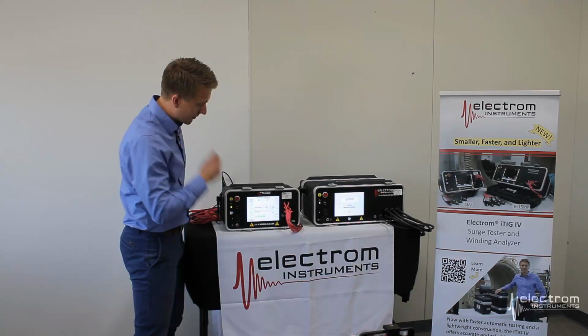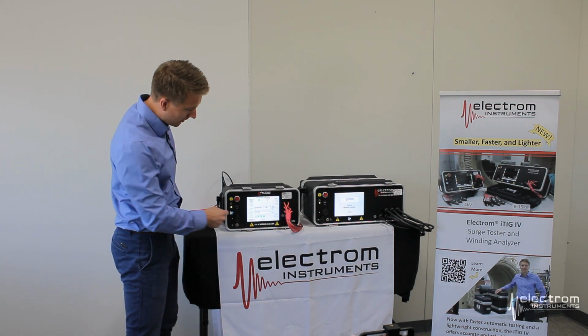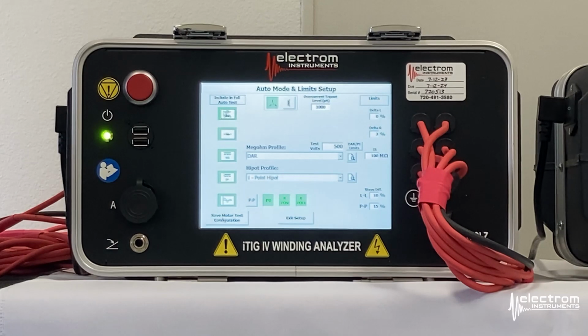At the top of the screen here, you can also select whether you're testing on a 3-phase motor or a single-phase motor. You can also select what type of profile to use for both the Megohm and Hipot test. In this case, we have selected a 1-minute dielectric absorption ratio test for the Meg, as well as a 1-point Hipot test for the Hipot measurement.